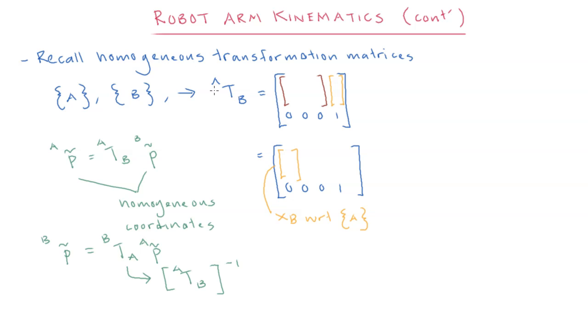So if we perform a purely rotational motion, or if we have rotated a coordinate frame, purely rotated without any translation, then we can use one of these 3 homogeneous transformation matrices. If we have performed rotation about the x-axis, then we have this.